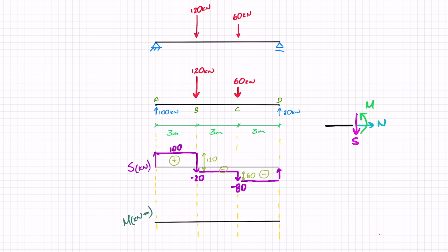It was a simply supported beam. In this case, I only have point loads. I've already found the reactions, I've already found the shear, and I can already see the only point loads here, and therefore my shear is just constant numbers in steps, as you can see here. What I've done is I have taken down interesting points, so when there are jumps in shear or when the shear crosses 0, and I've brought them down and prepared a line for my bending moment diagram.